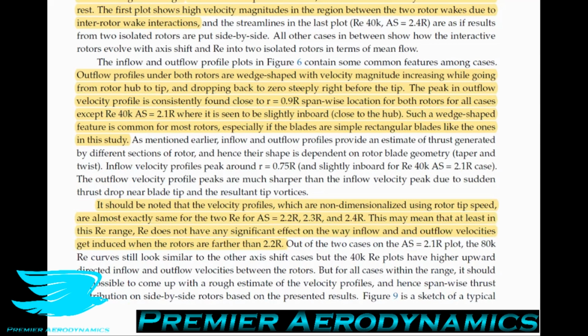Outflow profiles under both rotors are wedge-shaped, with velocity magnitude increasing while going from the rotor hub to the rotor tip and dropping back to zero steeply right after the tip. So let's talk about this quickly. The outflow profile is effectively what the wake is.